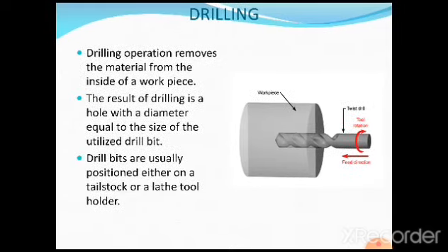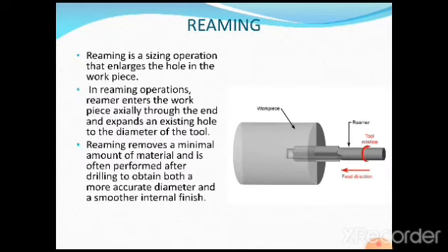The next type coming is reaming. Immediately after drilling, generally we go for the operation called reaming. So reaming is nothing but what? The operation of giving a fine finish to the previously drilled hole. This reaming operation is always carried out after the drilling.